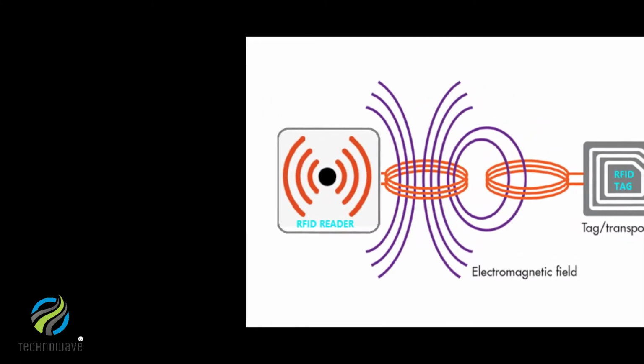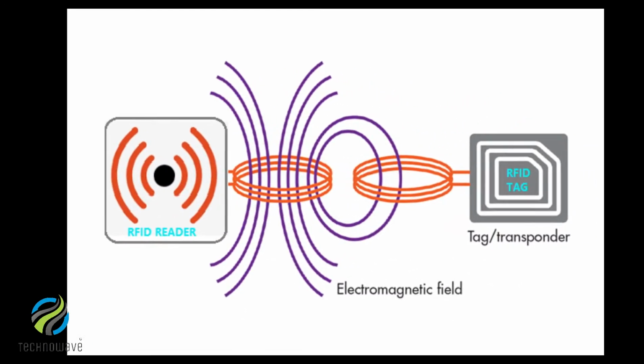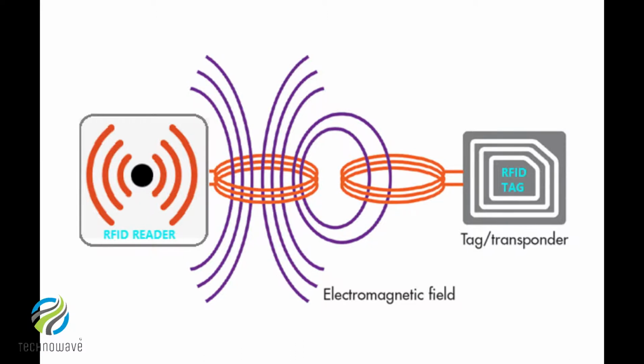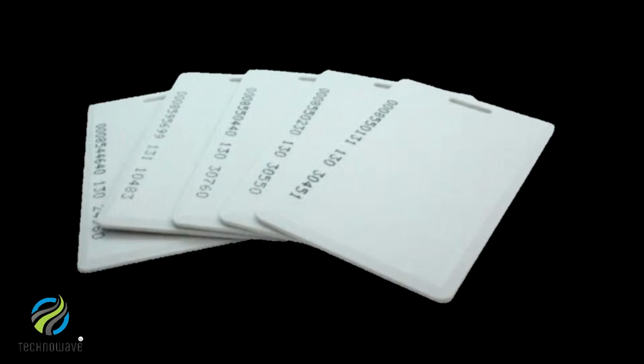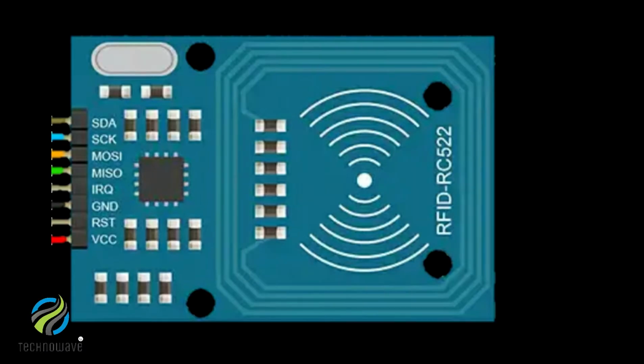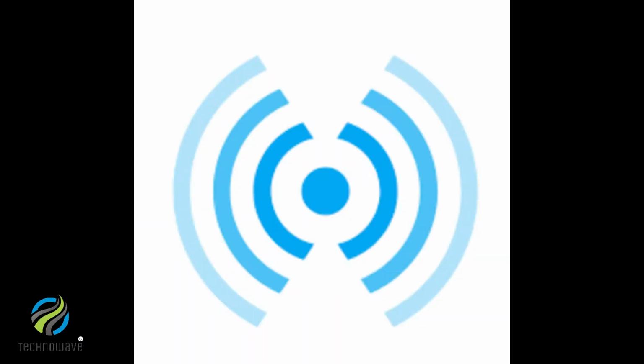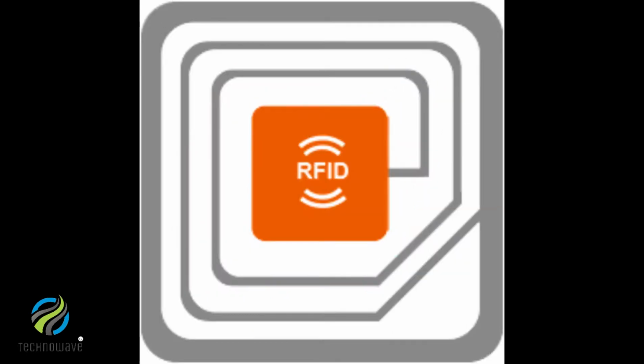Second is the reader. The diagram below describes the fundamental working of all RFID systems. The transponder or tag can be either active or passive. It reacts to the signals from the reader, writer, or interrogator, which in turn conveys signals to the system. Passive RFID system: these are systems where the tag gets power through the transfer of power from a reader antenna to the tag antenna. They are used for short-range transmission.